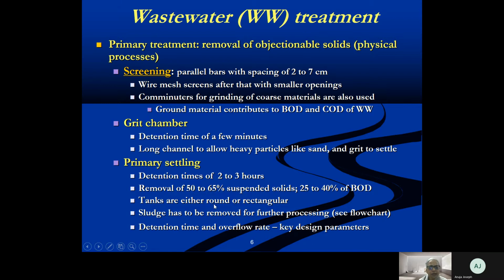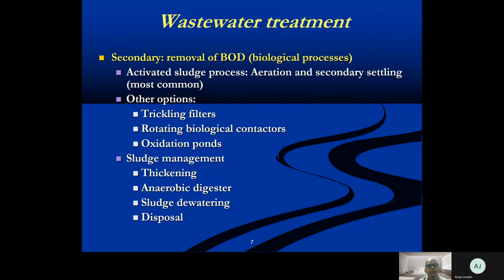These tanks can either be round or rectangular, and the sludge has to be removed further. We will look at that later. The key design parameters are the detention time and the overflow rate. I'll give you some practice problems. You'll be able to understand how to do them. They're very simple.